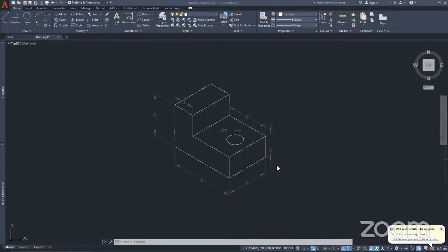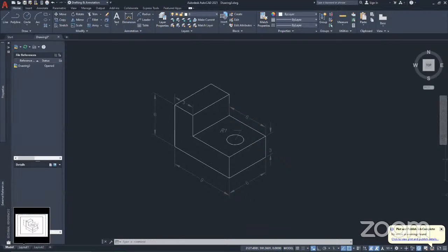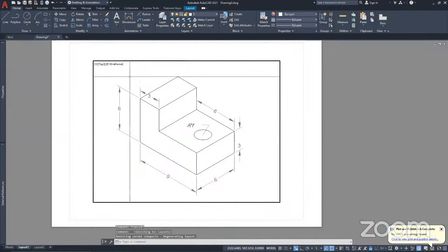All right. I haven't done that. There are other ways to actually plot or print. Now you can go to your layout tab. This printing was done with the model space. Now we can go to our paper space, like so, and then we can print.